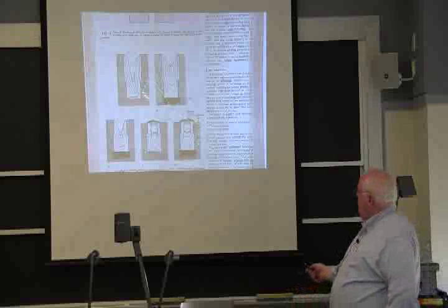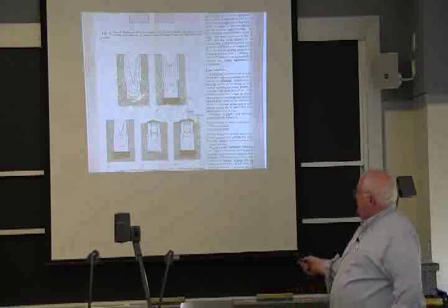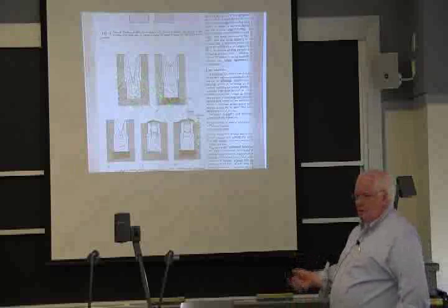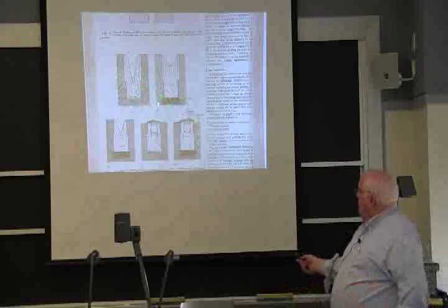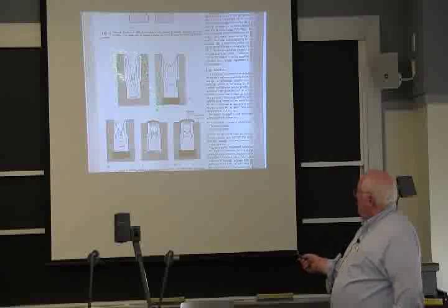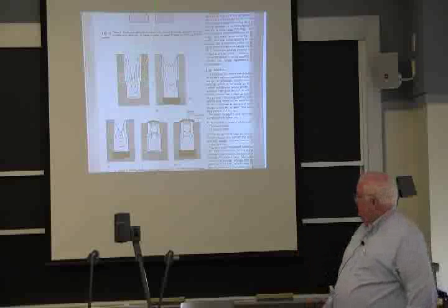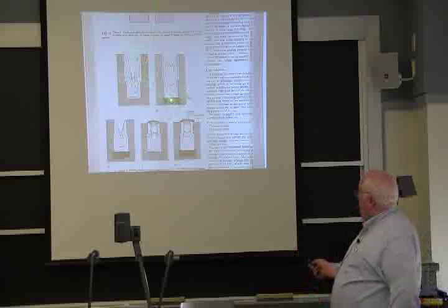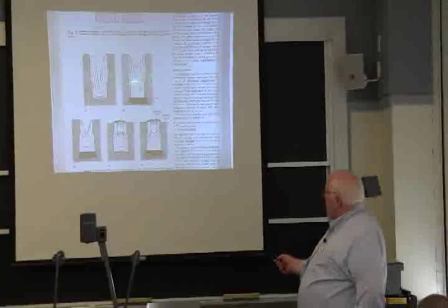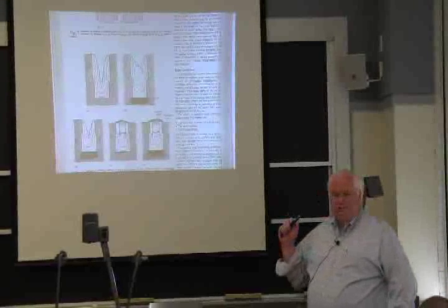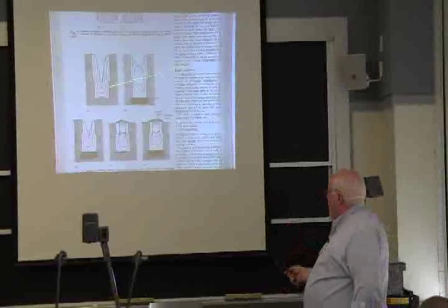So by putting chill blocks into the sand mold, you can change the amount of what we call risering. In the casting foundry industry, this thing above the actual part is called the riser. You're going to cut the riser off and send it back to be remelted. But if you put in chill blocks, you don't have to have anywhere near as tall a riser. Okay? You also can improve the structure.